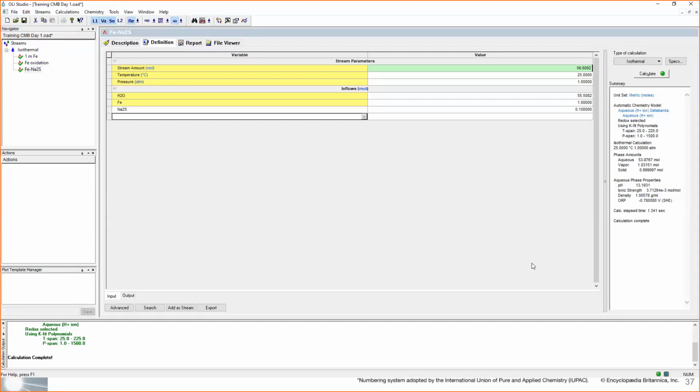And also, like I just showed, if you turn on all of the oxidation states, you will probably be generating a very long report with data that is probably not relevant or meaningful. So it is always important to know, if in your experiment you're certain that you have some specific oxidation and reduction reactions, and those create some specific oxidation states, those are the ones that we should take into account for our simulations.